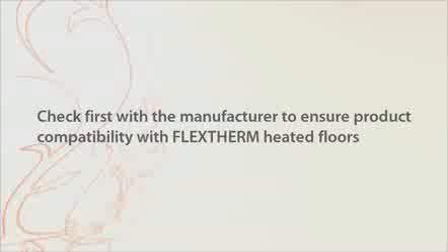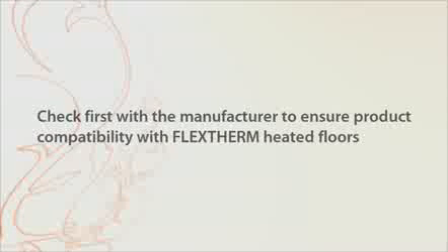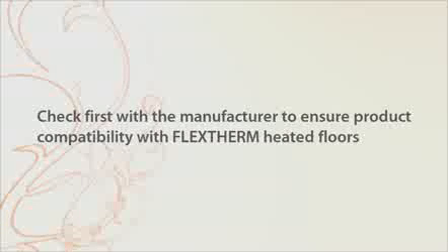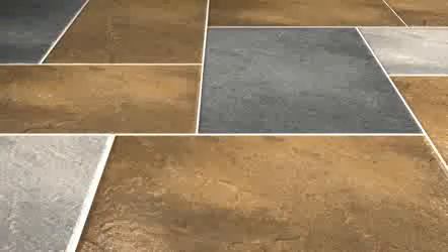You are now ready to install the floor covering. We'll look at 2 different techniques. Check first with the manufacturer to ensure product compatibility with Flextherm heated floors. Select one of the two techniques depending on the flooring materials: ceramic, stone, or other flooring.